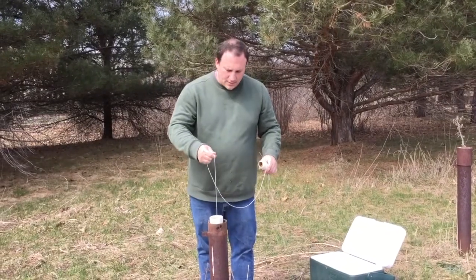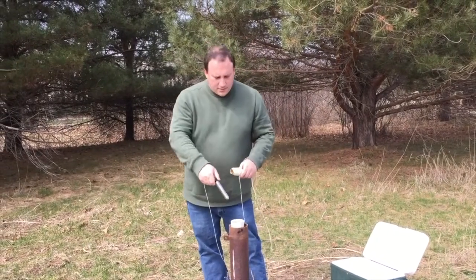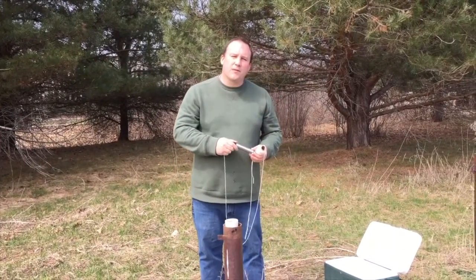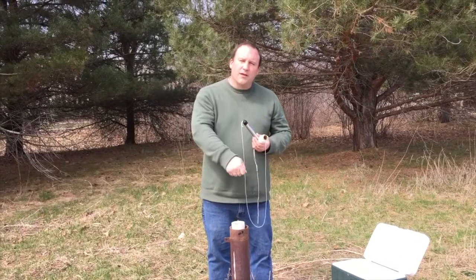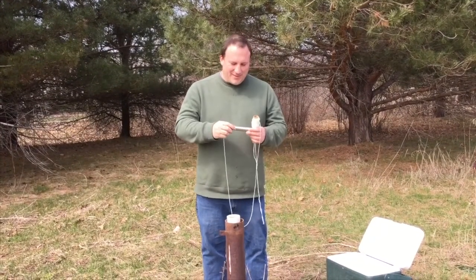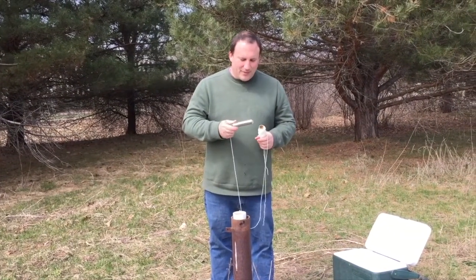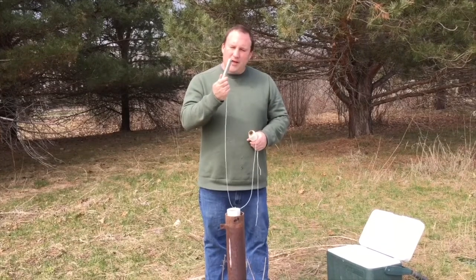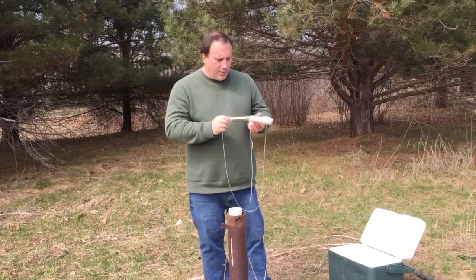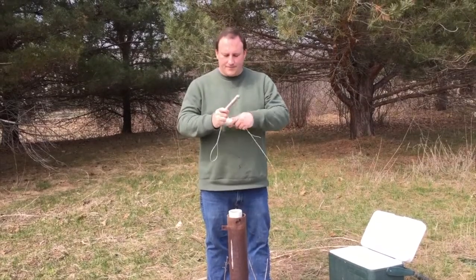Okay, so here's our data logger. This was down pretty close to the bottom of the well for both the slug in and the slug out part of it. I forgot and jiggled the depth meter a little bit on the way out or after I did the slug out. But we'll see what the data look like. Now I take this and connect it to the computer and we'll be able to figure out what the pressure was like in the well and temperature.